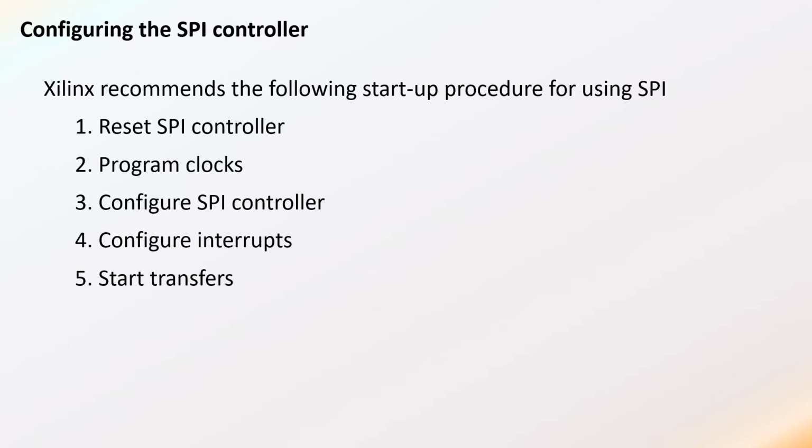So the unlocking of the SPI access isn't really central to the ARM. It's more having to do with the IP block itself. It's outside of the ARM process. So all that happens is someone designed a kind of a magic register that you have to write a known, semi-random key value to, and I'll show you what that is in a second.